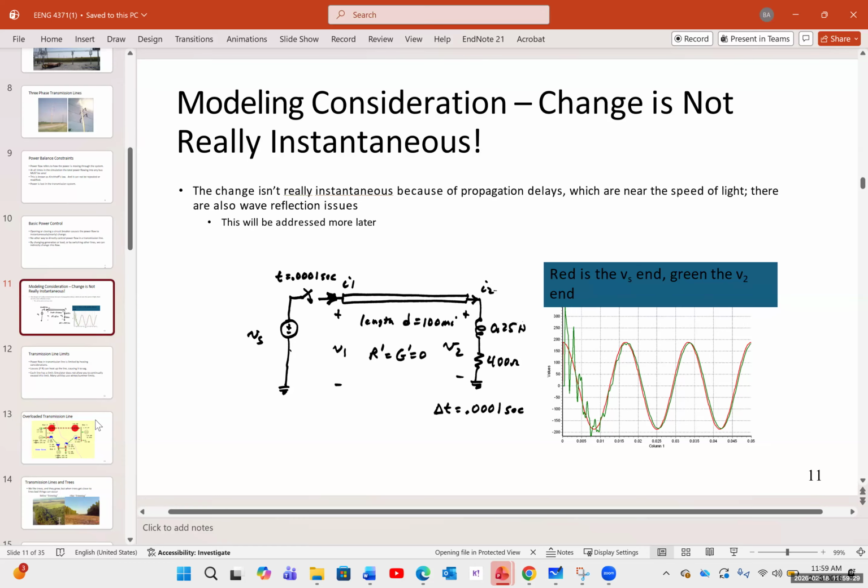And again, you can see the direction of the arrow shows the direction of the power flow, and you see the load, the generator, and also the generators and the load and the bus itself. Now, in this particular case, this generator at bus 1 is actually acting as a load as well. You can see that the generator on the left is producing 502 megawatts. The generator on the right from bus 1 is actually consuming 194 megawatts. So that's going to be also a bit of a problem.